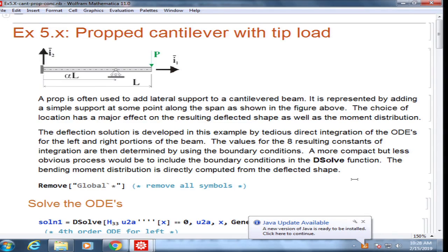Yeah, you are doing equilibrium on the entire slice now. Right. Equilibrium, you're just looking at the direction of the arrow. So if they're both in the same direction, they have the same sign. So there are two ways to solve this problem. Either you put equilibrium on the right side of the slice, for which V will be positive upwards, and you will do V minus P is equal to 0.